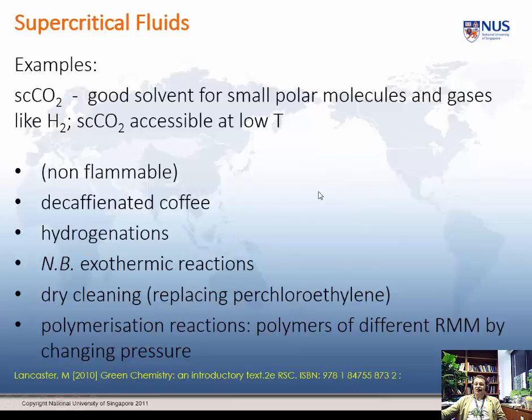Applications: decaffeinated coffee. You can use it with hydrogen actually to do hydrogenations. Note exothermic reactions. If you have exothermic reactions, that's something with supercritical fluids you have to watch quite carefully, because you don't want to be either it's not so much going out of the supercritical fluid range, it's actually runaway thermal reactions.